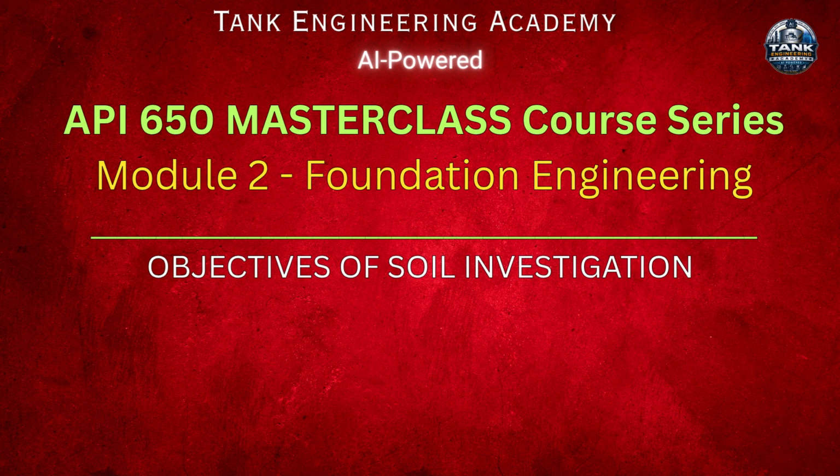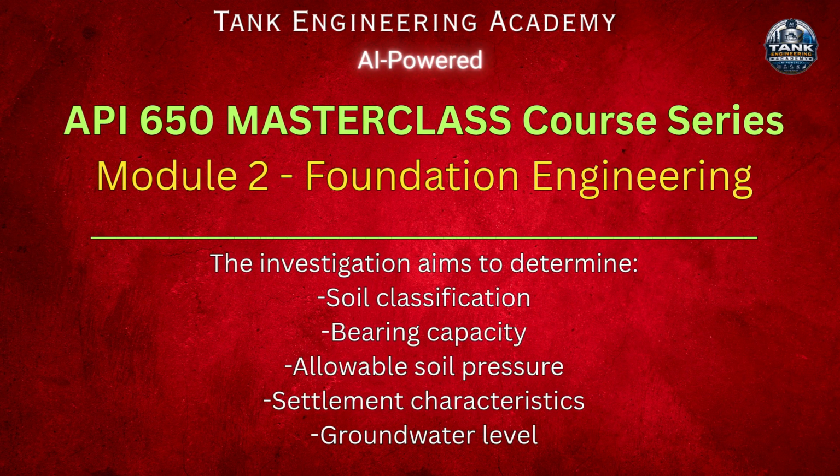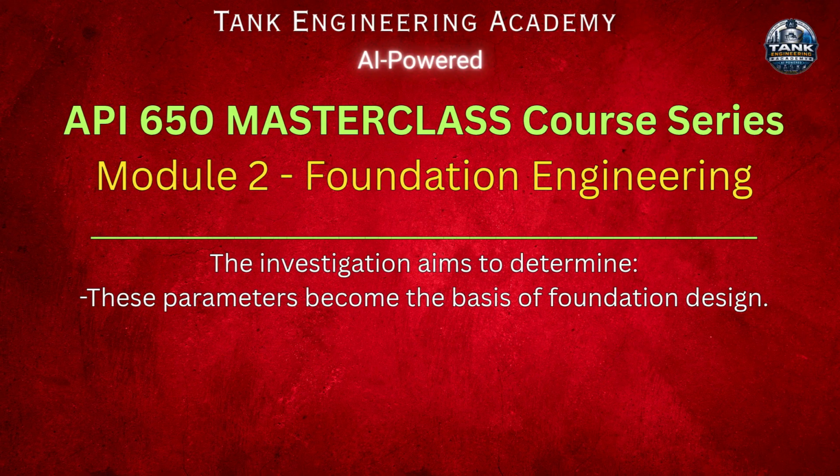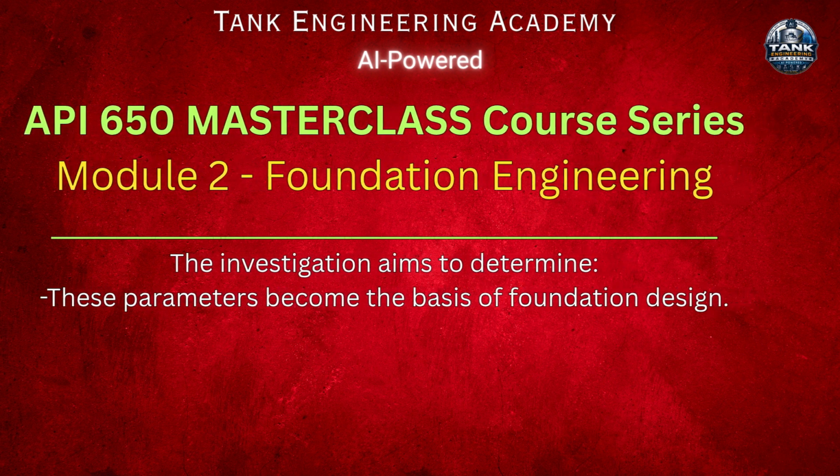Objectives of soil investigation. The investigation aims to determine soil classification, bearing capacity, allowable soil pressure, settlement characteristics, groundwater level, soil density, compaction characteristics, liquefaction potential, corrosive properties, and seismic characteristics. These parameters become the basis of foundation design.